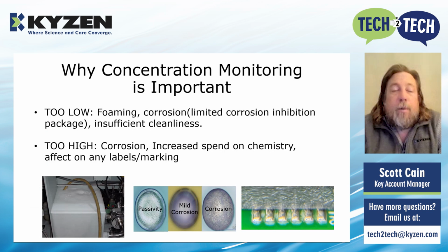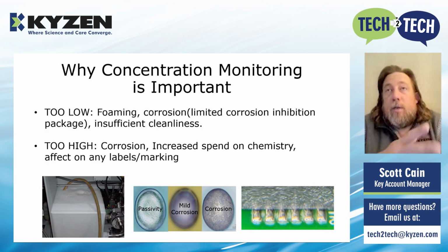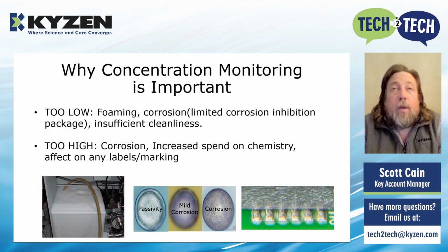So why is concentration monitoring important? Well, if we're too low, the chemistries are made up of a couple different ingredients that have different skills. One is a defoaming package. And if there's not enough of the defoaming agent inside of there, then we're going to see foaming. Additionally, we're going to see corrosion. This happens if the concentration is too low or too high. If it's too low, we're going to have corrosion from what's left on the boards. And if it's too high, the chemistry itself could cause some corrosion. And most importantly, if the concentration is too low, we're going to have an inefficient cleanliness. Whatever your cleanliness standard is, we cannot get there if the concentration of the chemistry is not high enough.